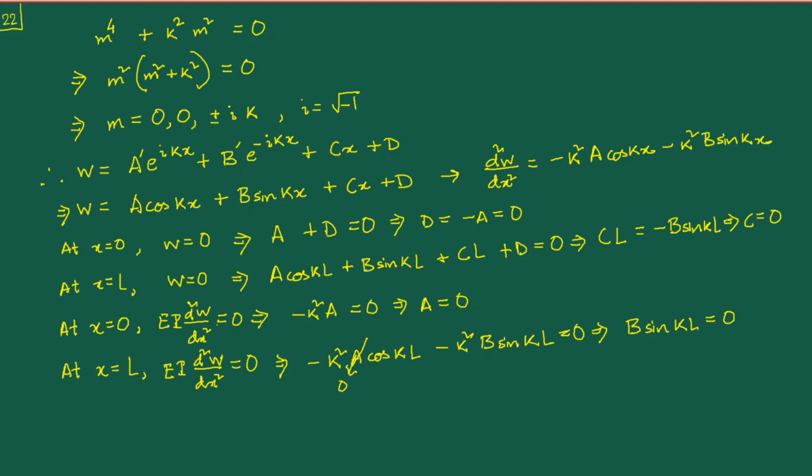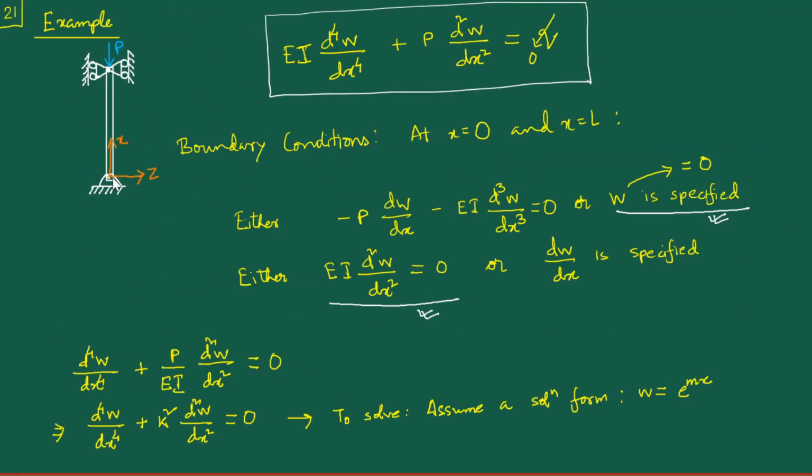What I mean to say is that if you look at this diagram, we would say that buckling is indeed occurring if there is a non-zero deflection in this z direction. So it really does us no good if we end up with a solution which says that W is always equal to 0.